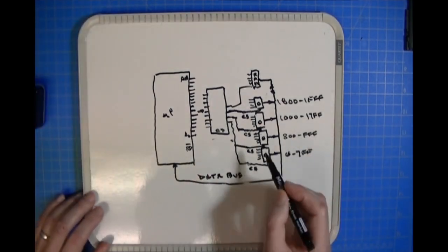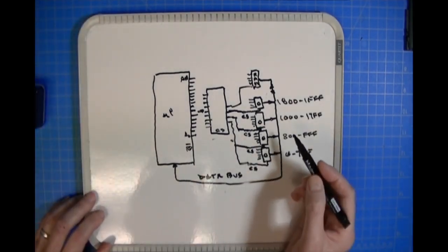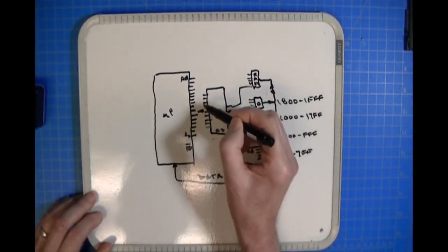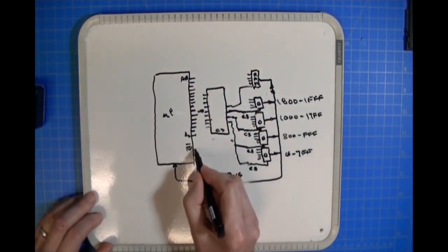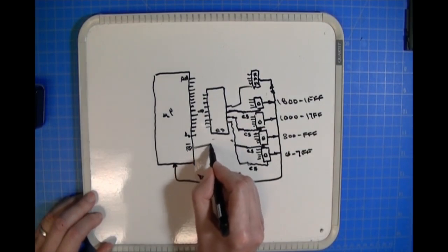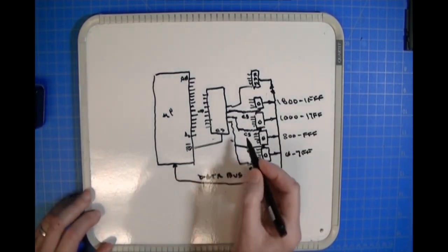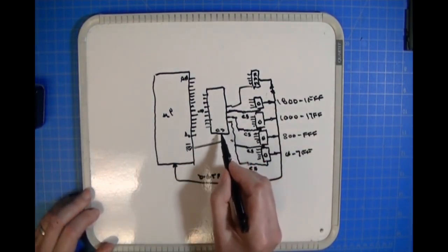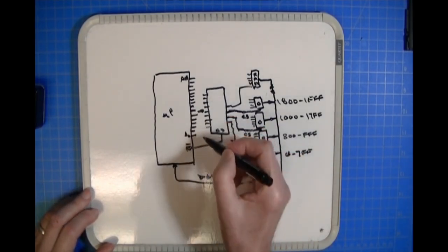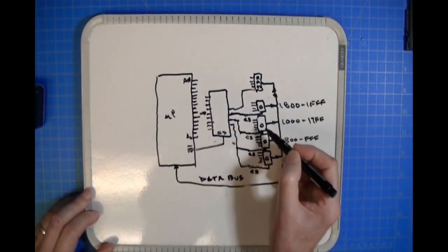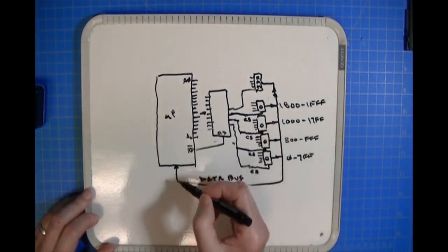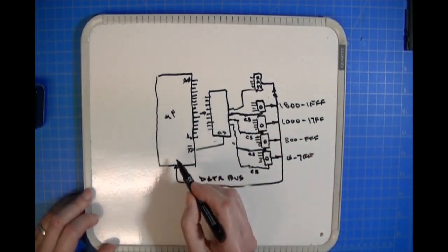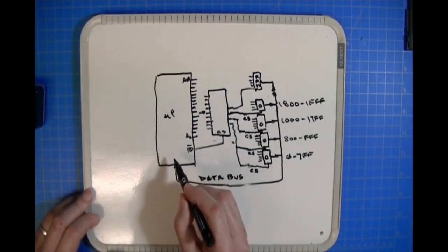Okay, so the bipolar PROM would do the decoding between these address lines, and then when the microprocessor issued its read command, the read command would activate the bipolar PROM. It would then decode the proper address and activate the appropriate EPROM, and the EPROM would then give its data back over the data bus into the microprocessor.